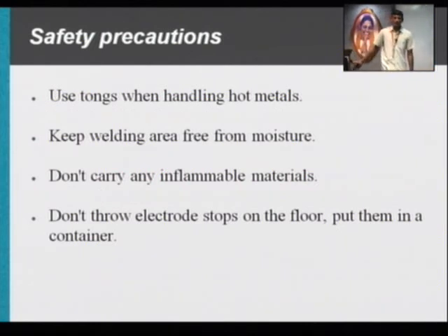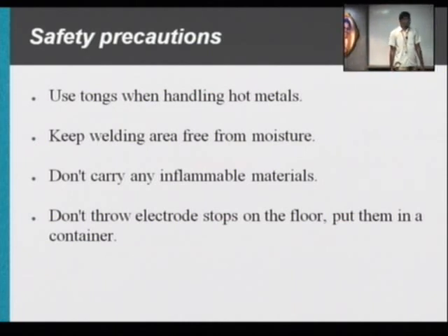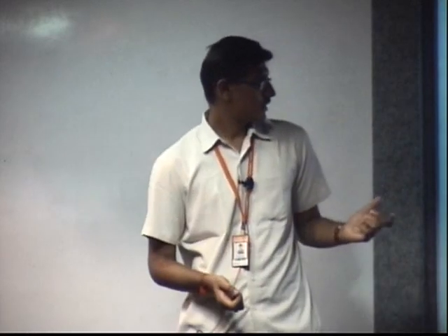After completing all the process in your lab, there are some steps that you should follow. You are not supposed to carry any inflammable materials, like firecrackers, matchboxes, etc. inside your lab, and use tongs to hold your hot metal, because after welding the base metal, that is your workpiece, becomes very hot, so you should handle your hot metal using tongs, and don't throw your electrode stubs on the ground floor.